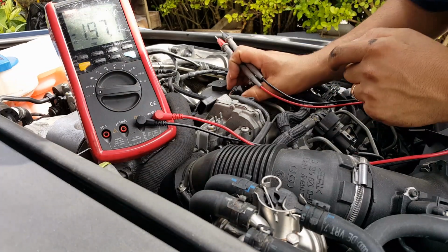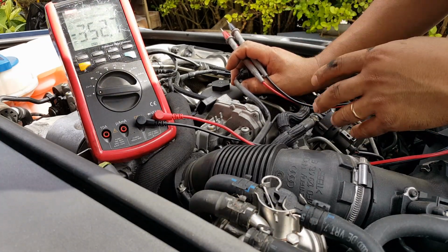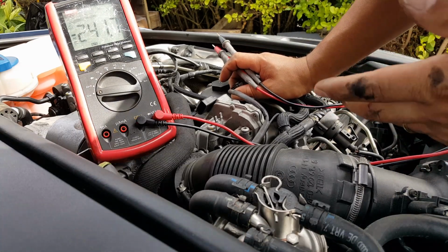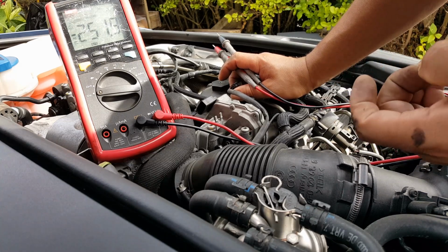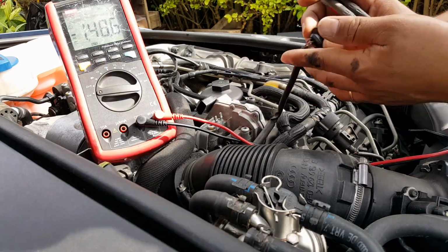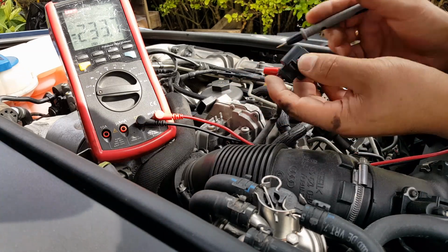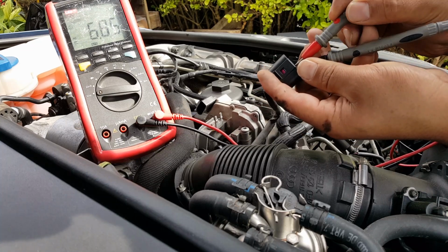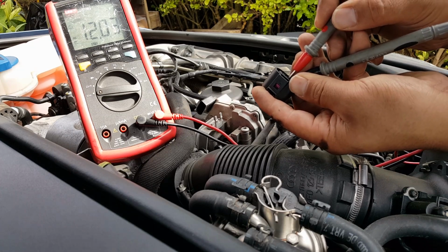Okay, so the first thing we're going to do is check voltage. If there's only one, I could check the basic voltage I know I should have, like ground, 12 volts at least. Because I have two, and one is working, I can just compare the voltage from one to the next. So we're going to check the good one first, the one on this side. I know the ground is the brown, or it usually is. Okay, so 12 volts on the first pin straight after ground.